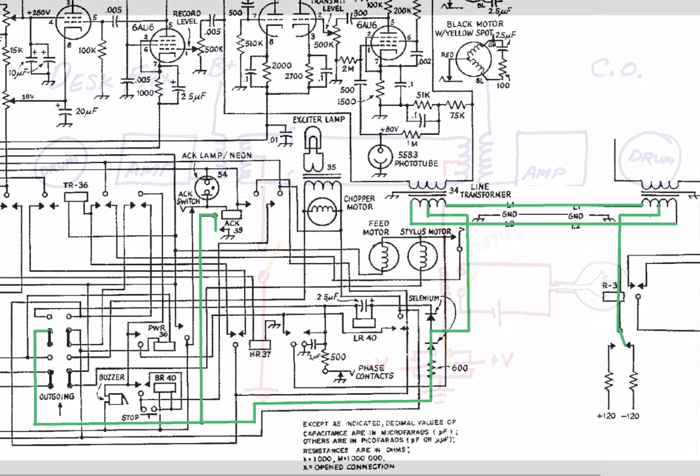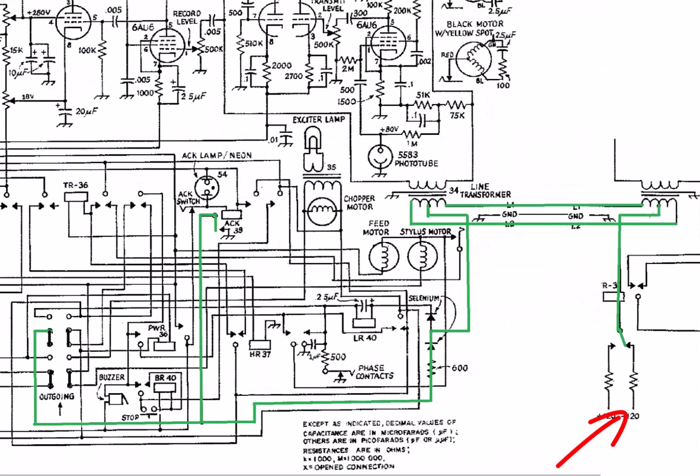So let's say that the central office has applied a negative voltage to the control line. If this DeskFax leaves that as an open circuit, then no current will flow, and that central office relay, the example that I showed earlier, will not energize. And this is, in fact, the idle state of the machine. When in idle, the central office puts minus 120 volts DC on that line. The DeskFax leaves this as an open circuit, so no current flows, and there it sits.